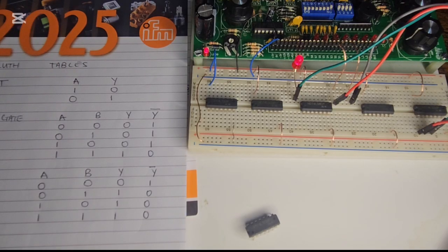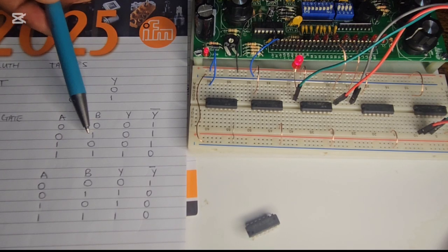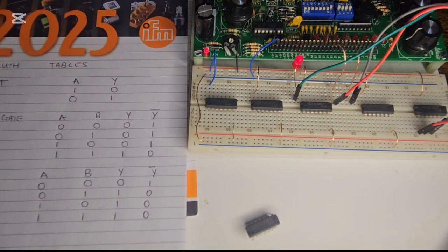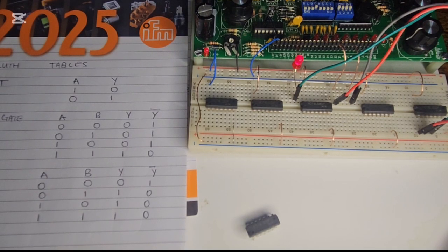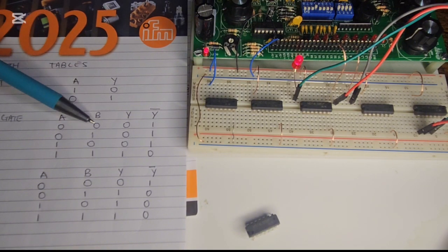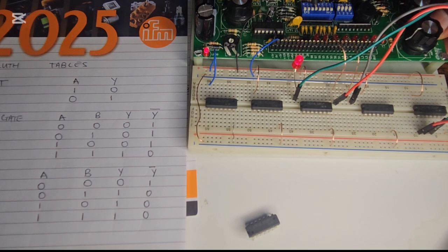Okay. Let's just go with the steps. We said a 1 and a 0. Now we're going to say a 0 and a 1, which is this one goes to 0. This goes to 1. Again, 0 and a 1. My output is still on. And then a 0 and a 0, meaning both switches are off. I'm still getting an output that is true. So this matches the NAND gate.